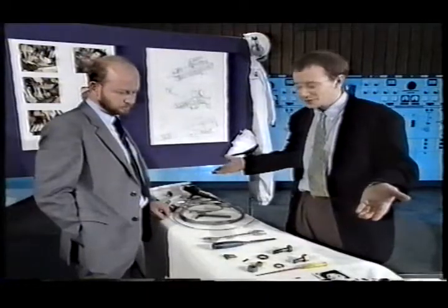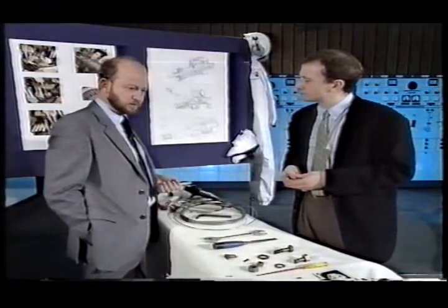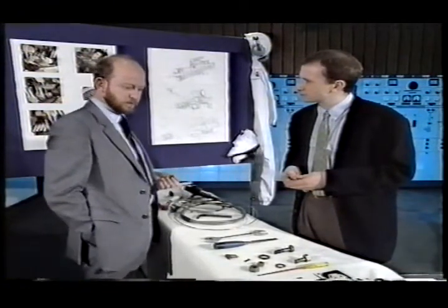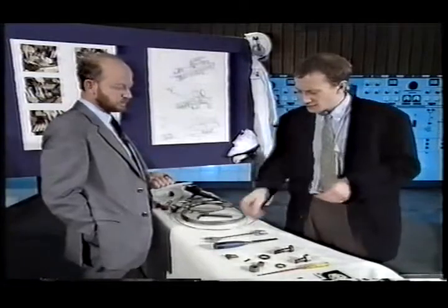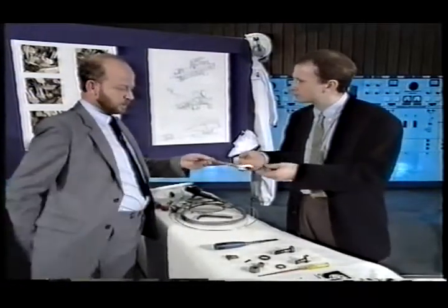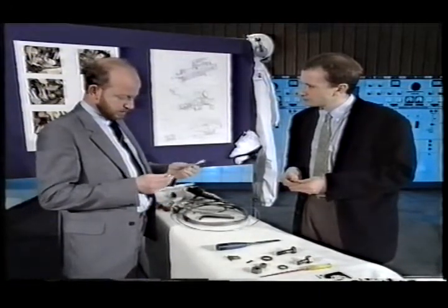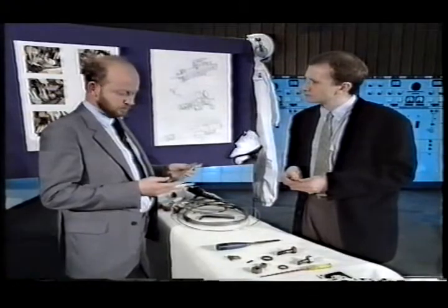So, Nick, what are all these objects? Well, they're a selection of items that have been either found in machines or of the resultant damage caused by such items in the machine. And what about this spanner? How does a spanner cause a machine failure? Well, a spanner very much like that was found inside a generator in many pieces that had been in the air gap between the rotor and the stator and caused severe damage to the machine.